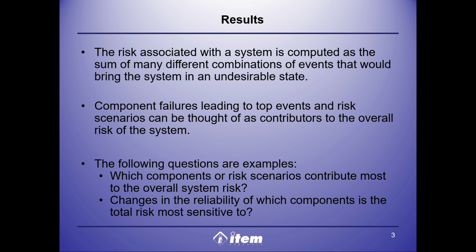Before we look at the software output, let's establish exactly what a cut set is. In systems reliability modeling, a cut set is any group of basic events, which in our case are component faults or human errors, that, if they occur together, will guarantee that the top event happens. If you trace the logic gates from the bottom of our reactor vessel tree all the way up through the intermediate gates to the catastrophic G-explosion top event, a cut set represents one unbroken, complete pathway to failure. It is the specific scenario of events that breaches our defense in depth.